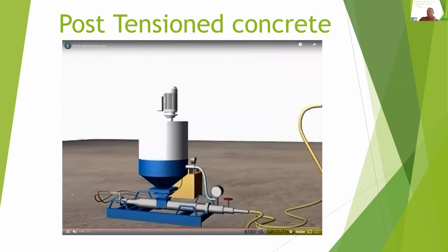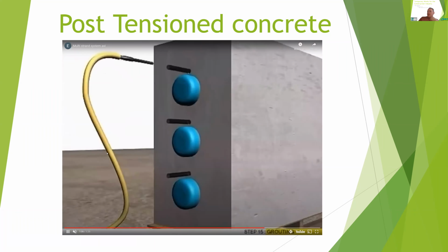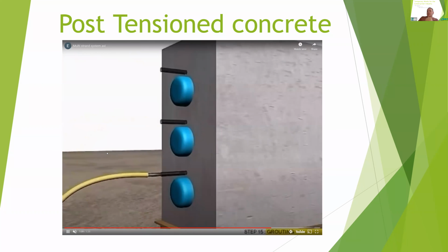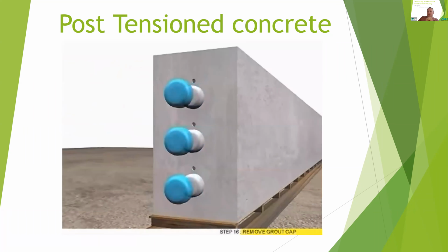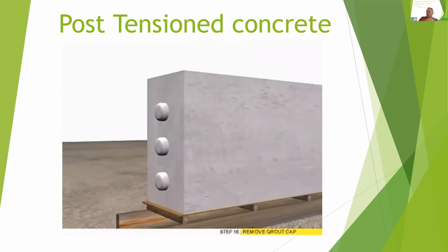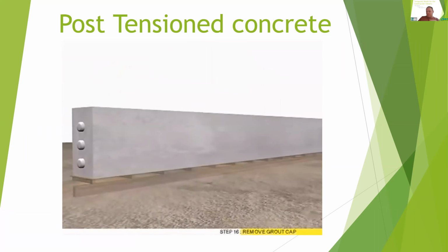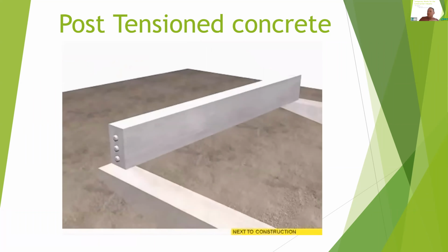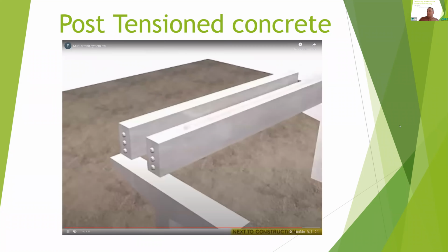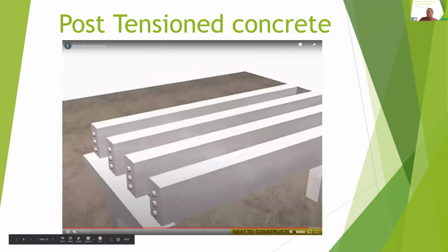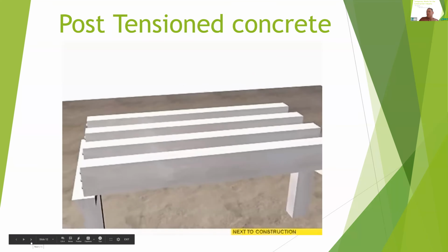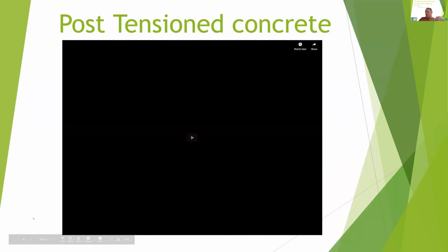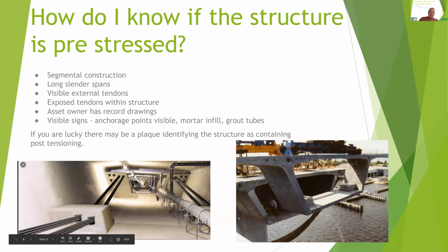And then pump grout into them. Now the other function of the grout is it stops any long-term rusting or failure of the tendons, which can be quite a big problem with post-tension construction. And then you can lift them into place, whatever your structure happens to be. So you don't necessarily have to do it in situ. You could do it on the ground and lift it up, which case study later on, they've done just that, which I'll go through.